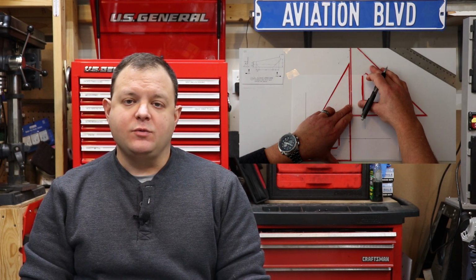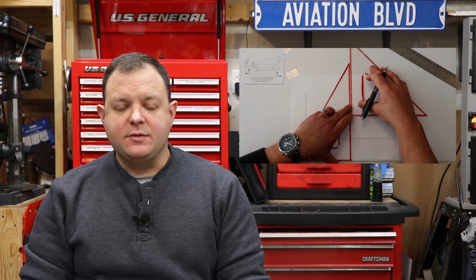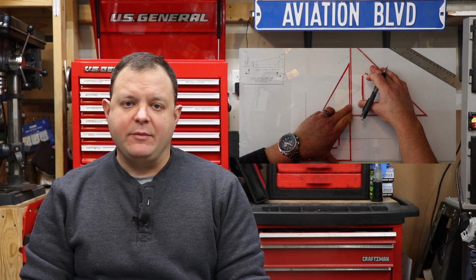Drafting is the general term used to describe the act of creating a technical drawing or set of blueprints. Drafting is also the process we use to lay out parts using precision instruments and tools at the beginning stages of fabrication. Any set of technical drawings will contain symbols, perspectives, units of measurement, notations, and other information needed to physically create what is shown. Drawings of individual parts consist of boundary lines, hidden lines, and measurements for locating specific features of the part, such as holes, bend lines, machined areas, and other bits.